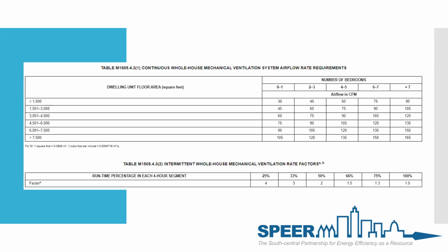ventilation rate. The only problem I have with that, which is not yet addressed in the code, is in our warm and humid climates, there is no requirement or limit set on what is too much. So if you have an air handler being used as its fan source, you've got a 6-inch duct and the damper just opens and closes every time the unit runs. Well, when it's running in the winter, it's drier air outside, but when it's running consistently in cooling, if it runs long enough, it should pull humidity out. But really what it's doing is pulling uncontrolled humidity through there.